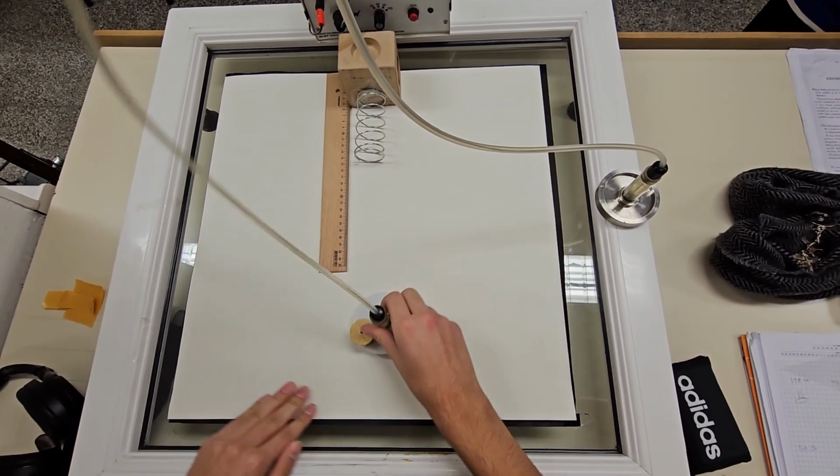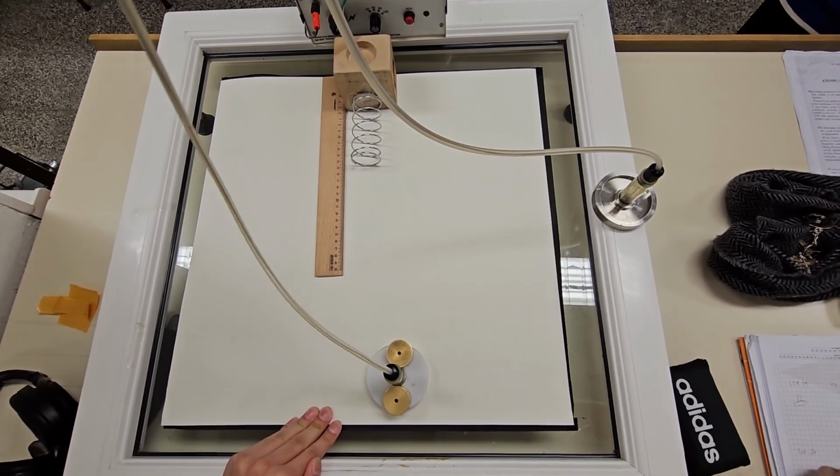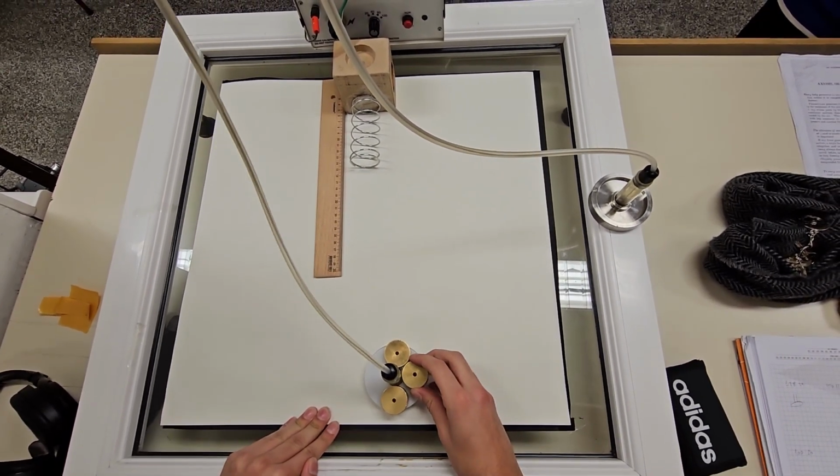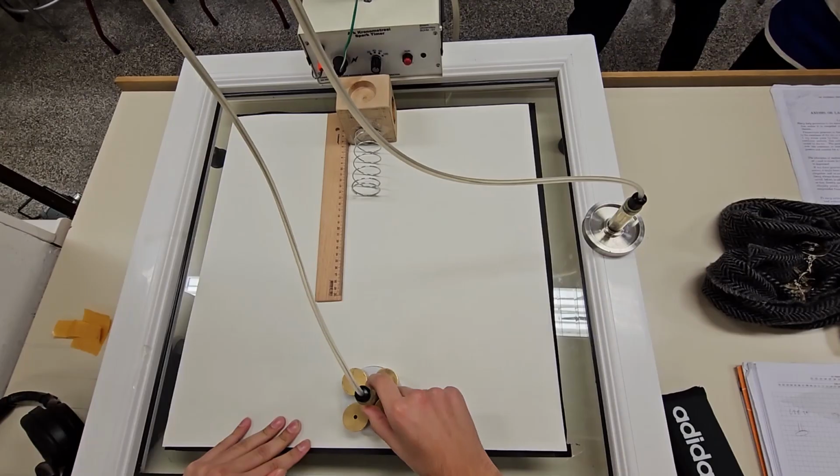We will do this by assuming that at the instant the spring compression is at maximum, all kinetic energy is converted into spring potential energy. By using the equation 1/2 kx squared equals 1/2 mv squared, where k is the spring constant of the spring, x is the distance of the spring compressed, m is the mass of the thrown object, and v is the velocity of the object, we will be computing the constant k by experimentally measuring all other variables.